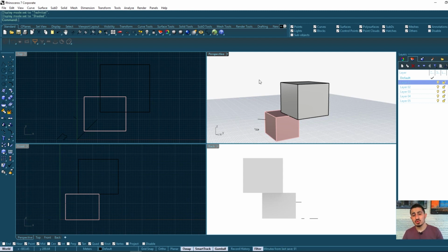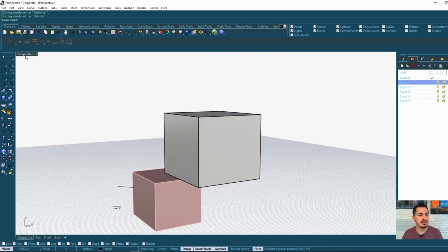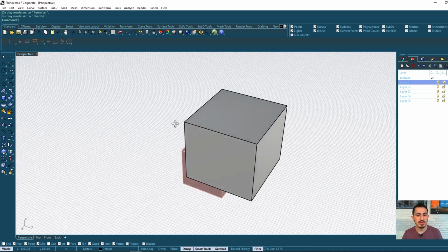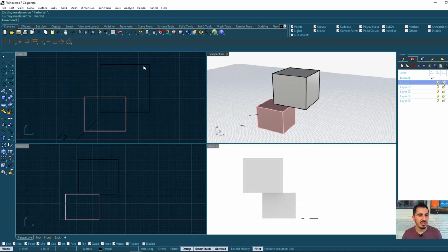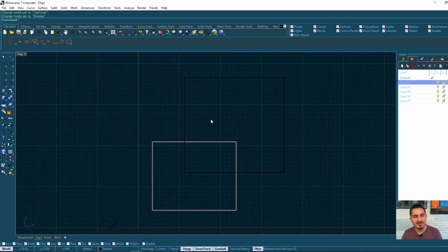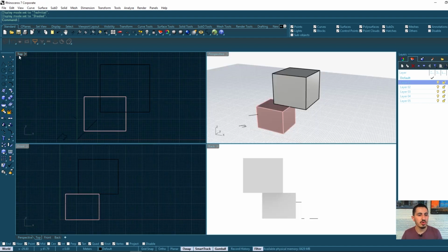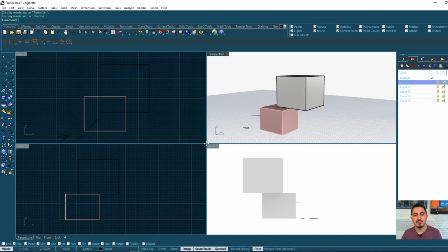And of course, if you want to work with only one view instead of 4, that's basically if you double click on the name of this view, it will become one view, and double click again to come back to the other views. A lot of the time when we are working on the plan, we can come to this view, finish our work, go back, and work with the other views, so this is a helpful tool.